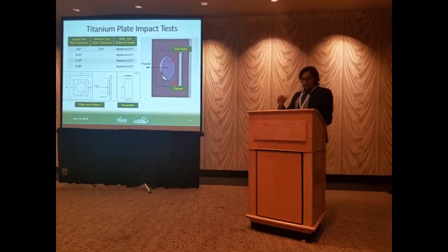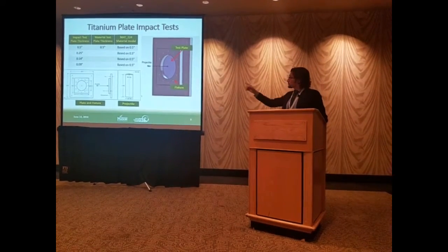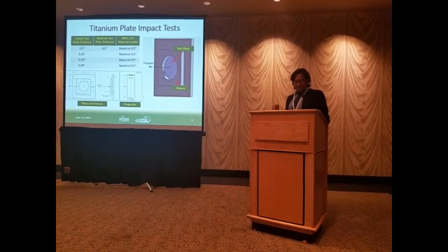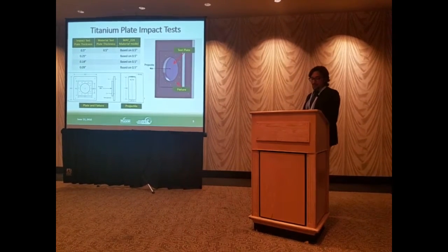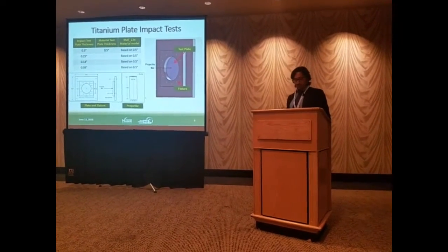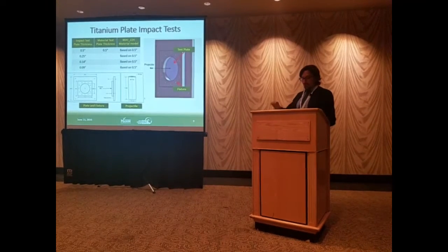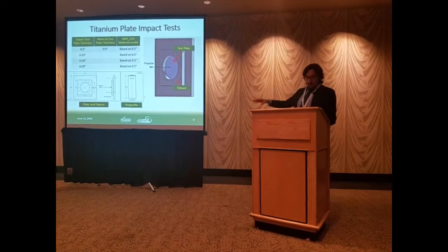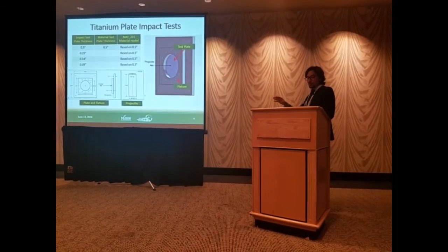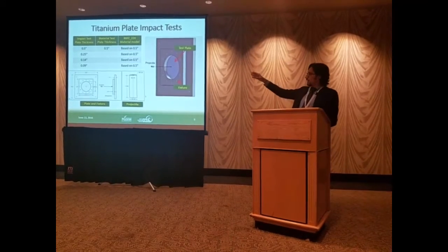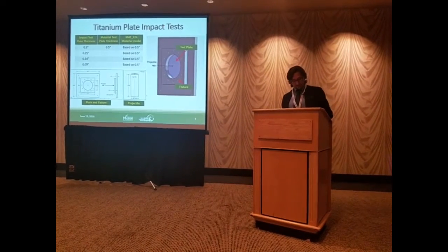And the half-inch plate impact test is the same used in the material test. And based on that, we developed the MAT224 material model. But for all the other thicknesses, we always use the MAT224 material model based on the half-inch material test.